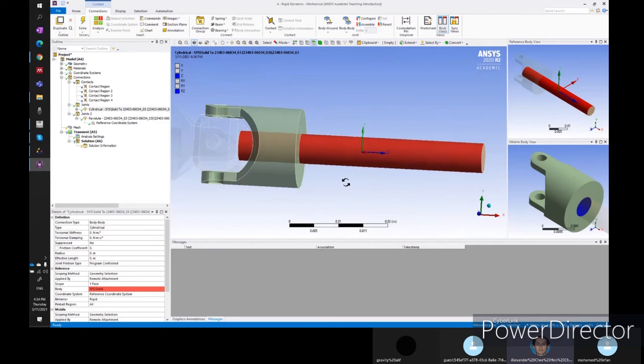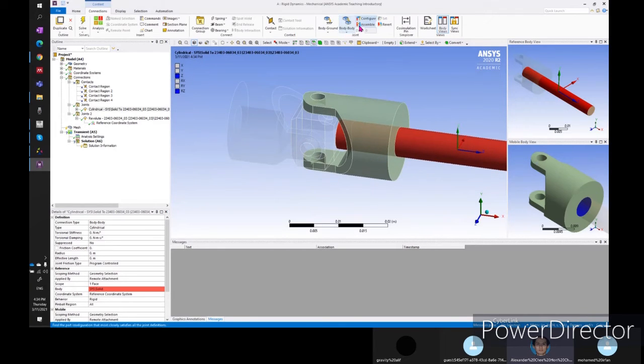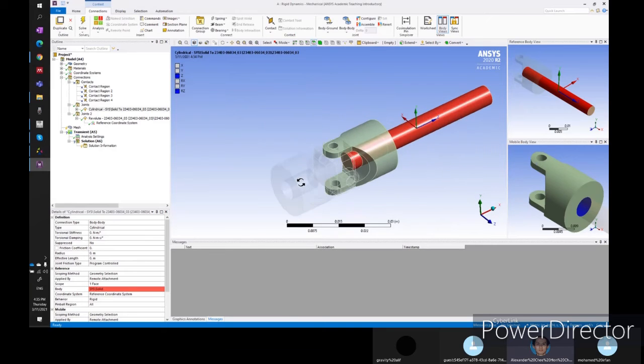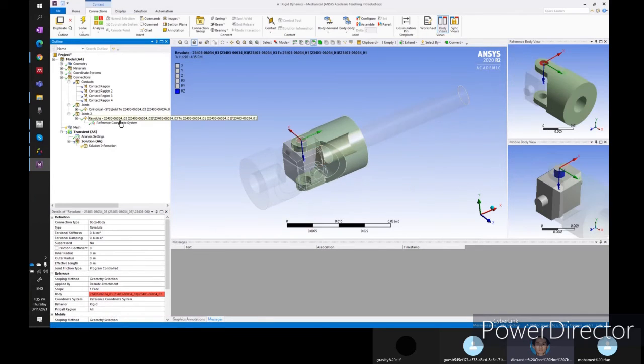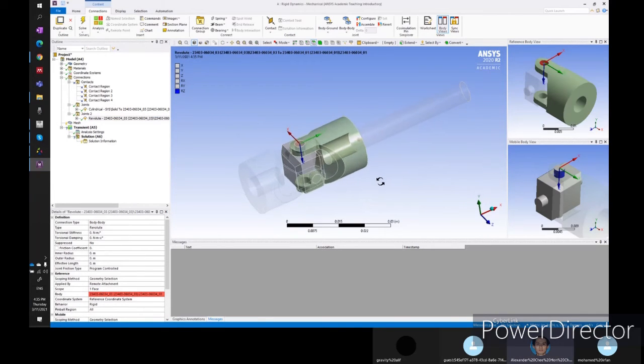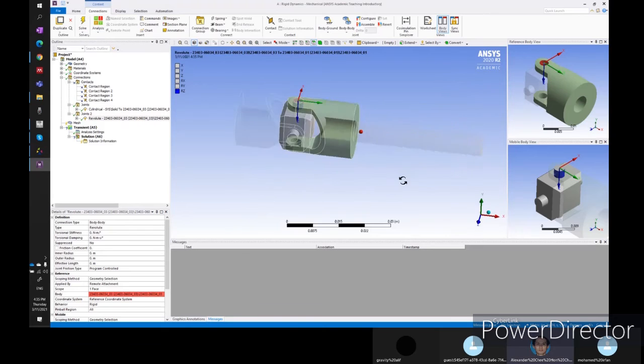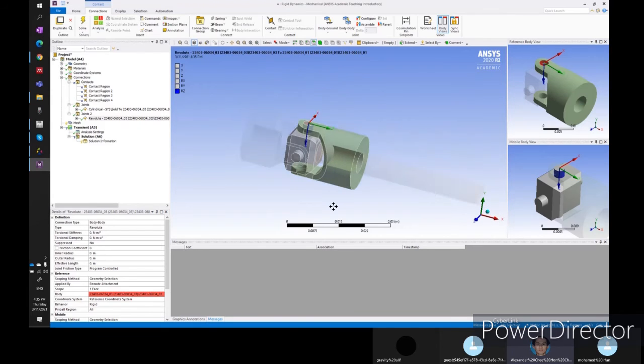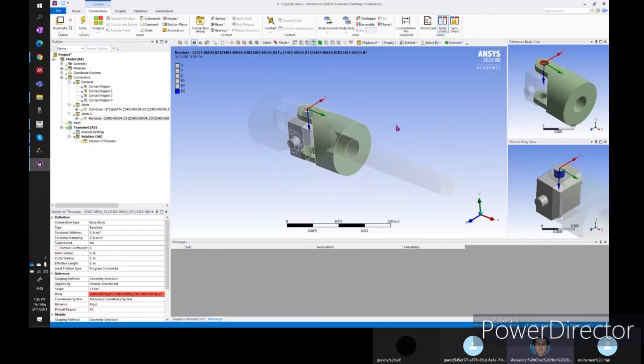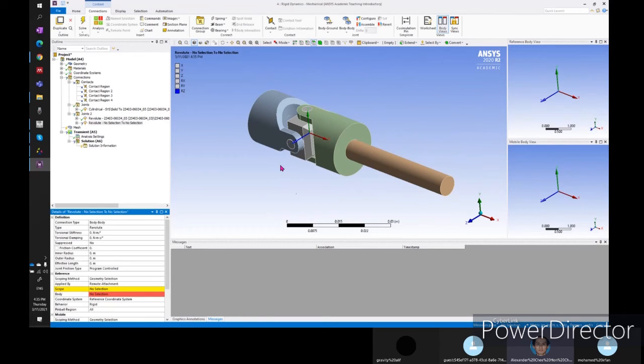So from configure, if we put all the joints correctly, we can see before we simulate that the movement is correct. And you must know your design. So now I will do it fast for the remaining 3 joints, the left, right, and the bottom. Okay, I will do it quick. You do yours, okay? I don't need to keep explaining because the work is repetitive. So now I will use that again.